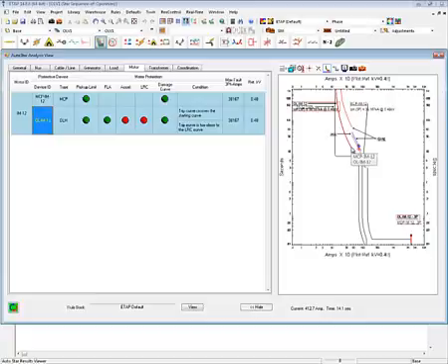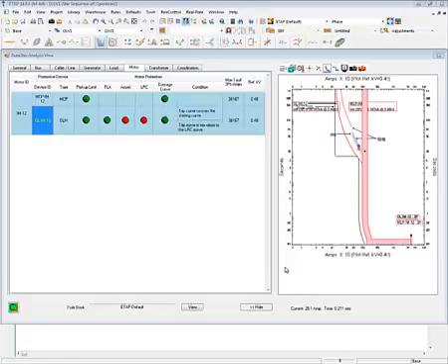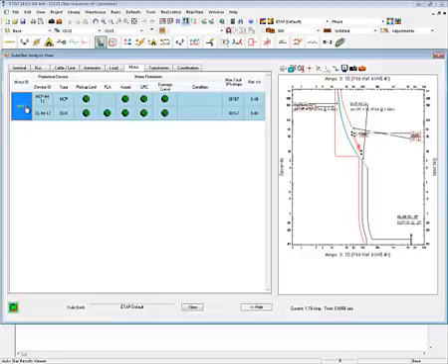So again, I play with the setting of the overload heater and adjust it to a level where it won't intersect with the curve, and the software, by way of the result viewer, tells you that your system is properly protected now. This product is under development and we can discuss more about it in future. At this moment, I will pass on to Steven to discuss the sequence of operation for arc flash.